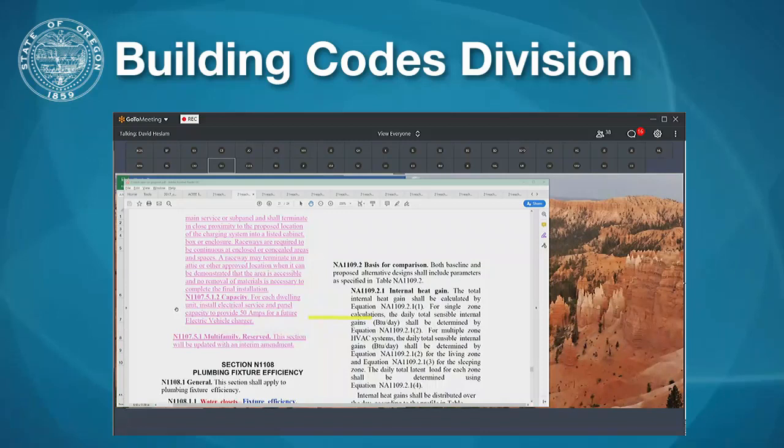That would be the load of the charger that the electrician would have to plan for when designing the overall service size for the home. So the breaker would need to be larger than a 50 amp. The load, again, you're going to get beyond my experience. If there's an electrician here, help me out. But 50 amp was stated as the largest that anybody would foresee there.